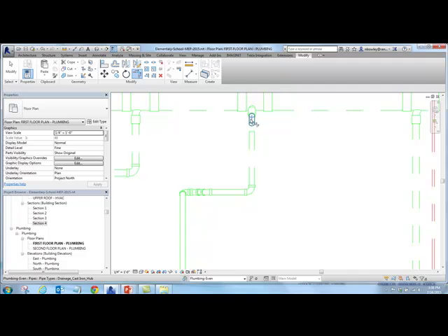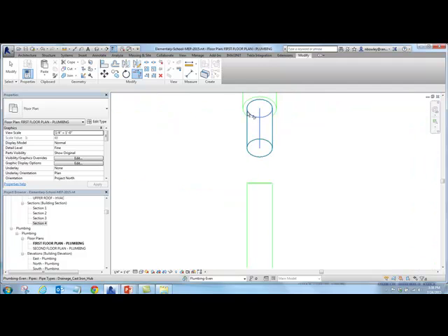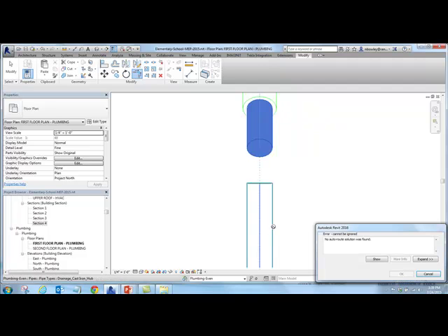When you do the trim and extend to corner, pick pretty close to that T because you don't know how long that branch is going to be. So when you use trim and extend to corner or fillet, in the CAD days, you would pick the part you wanted to keep. It's the same thing here. But if I pick up here and that's higher than the pipe I'm connecting into, it's going to connect the wrong way. It's going to do like a 135-degree elbow. So click pretty far back to your T. Click on your branch that you were just doing.